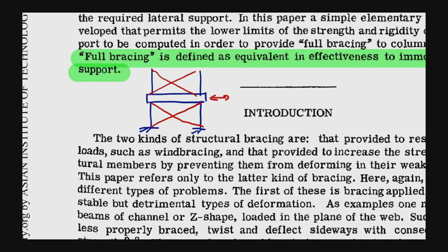And as you have learned the dynamics of structures already, and the earthquake and wind already, you know how to figure out the lateral force. So knowing that, you put it in the structural analysis program, and you will get the force magnitude in the brace.